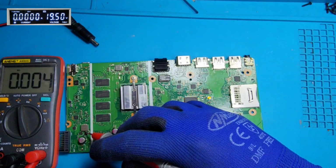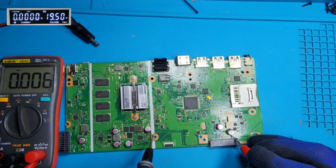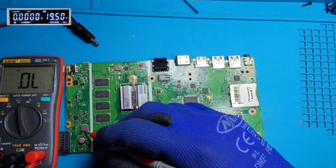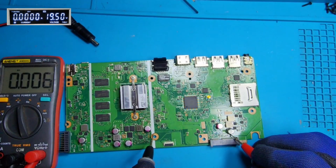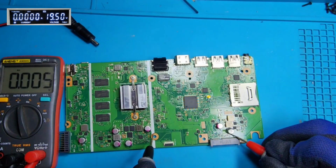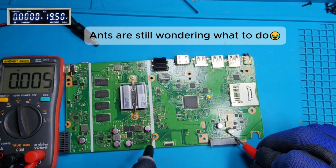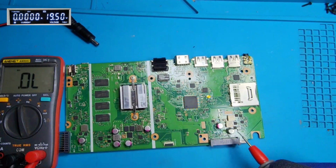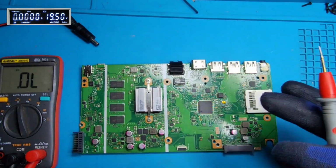Oh, we have 4 here. Somewhat similar to this one, but less than this one. Let me check it again. 5. Yeah, that is actually the same. So this coil and the main power rail have the same impedance, which is very low, and that is unusual.